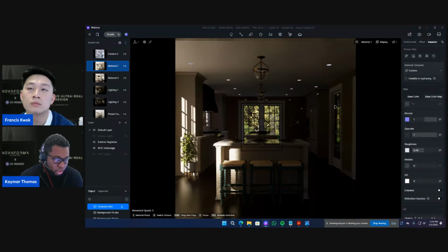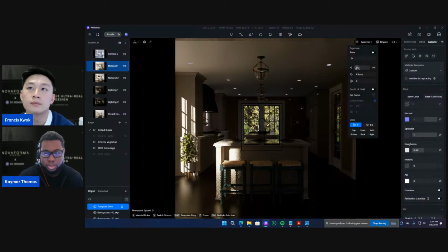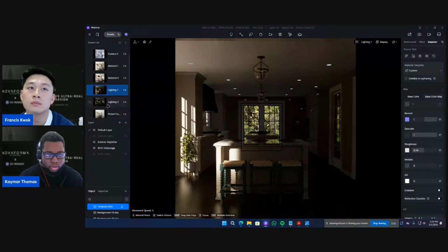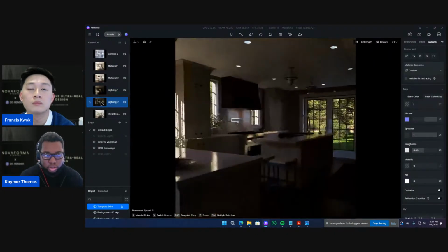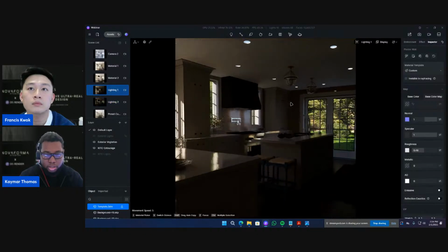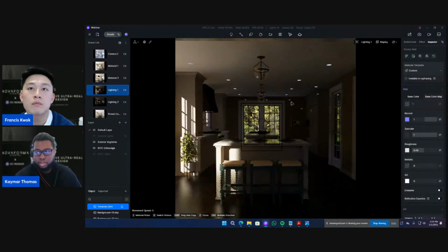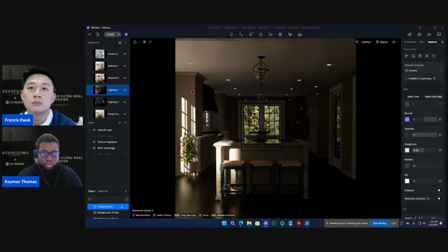So we keep it at 0, turn off auto exposure, and then you start to end up with these lights naturally, which is just the sunlight beaming in. The general rule for light that we use is a 60-30-10. So in a daytime rendering where the sun is outside, you want 60% of the light in your overall render composition to be from outside.